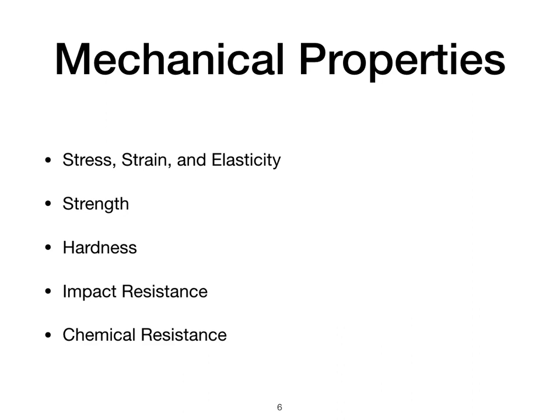Applied stress can be homogeneous. The strain describes the deformation of glass. The elastic nature of glass is described by its elastic moduli. So these moduli tell you a lot about how much a glass will deform under stress and in what direction it will deform. Three important and commonly used elastic moduli are Young's modulus, Poisson's ratio, and shear modulus.